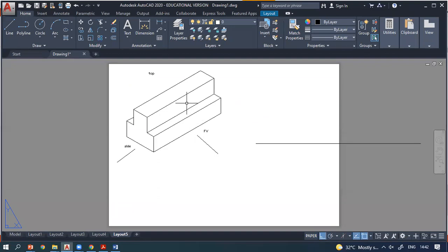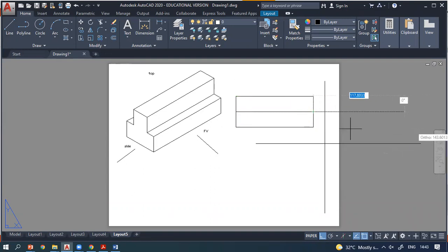I can see this surface and this surface. So xy line and x1 y1. The front view is like this, 100 mm and 20, 100 and 20. This corresponds to this lateral surface, and I can see this lateral surface. For that, again, it is 20, 100 and 20. So in the front view, I can see only two rectangles.